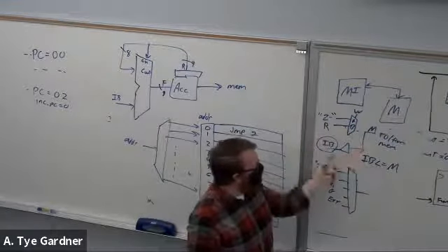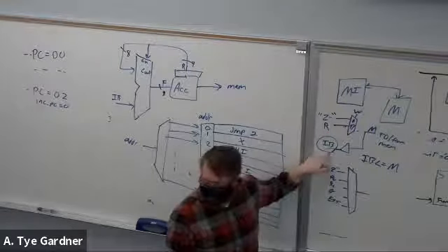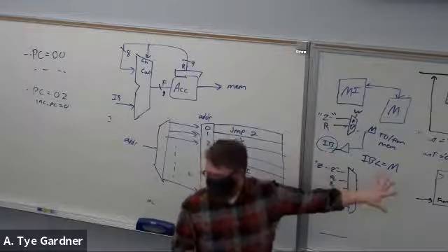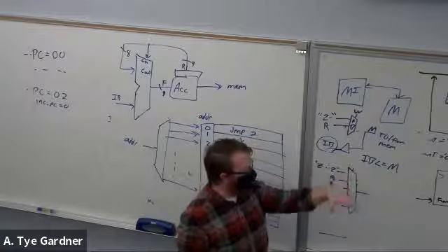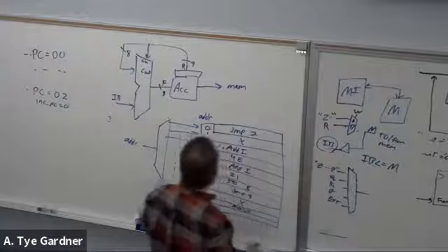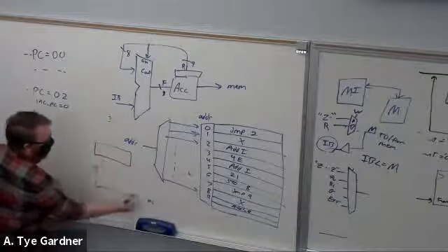The next thing that happens is we set write to 1 so that we're R. That feeds back R, the contents of the accumulator, to the internal bus. Now this time we don't tell the memory it has to do anything, because we don't want to put that memory address back in. We just take this, we want it back on the internal bus. Now it's appearing on the internal bus, and of course, as soon as I said I don't need it anymore, I need it.